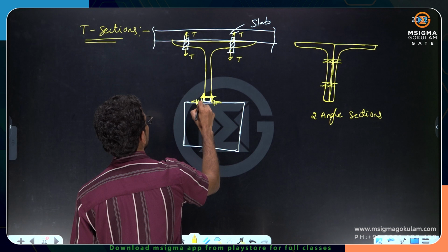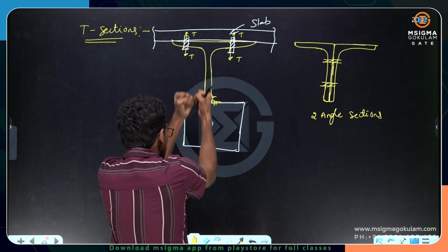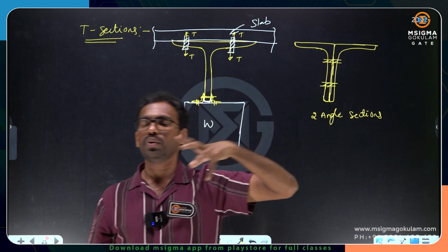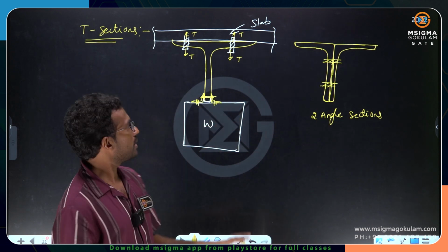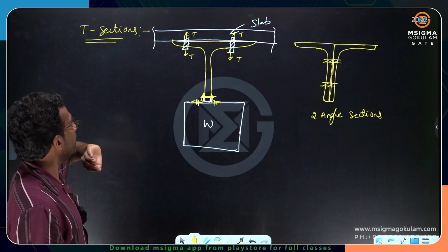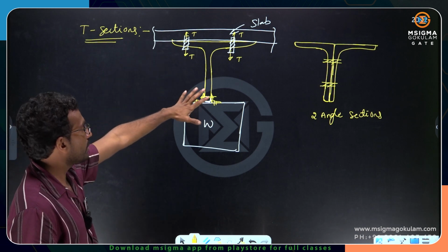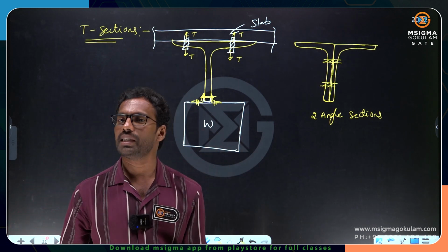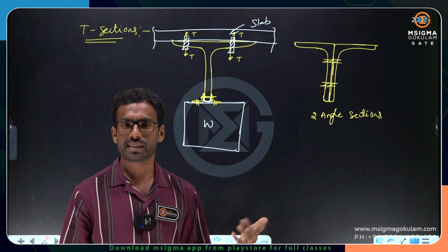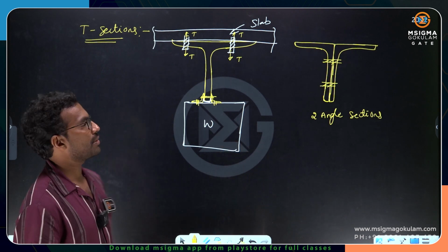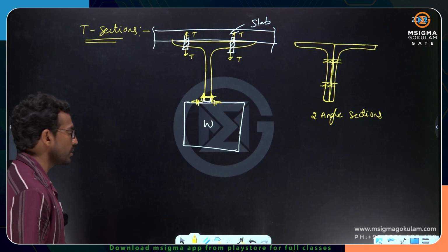Then this weight, whatever is pulling down, is going to cause tension in the bolts. Then bolts are undergoing the tension here. That is what exactly happening over here. Okay, so overhang connections we use the T sections. T sections are used for overhang connections, and these are also provided as stiffeners in some cases, water tanks, etc. There is no other much significance of these T sections when compared to the other sections.